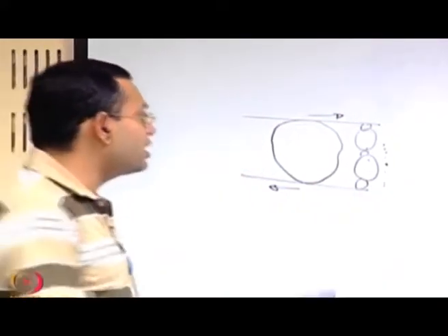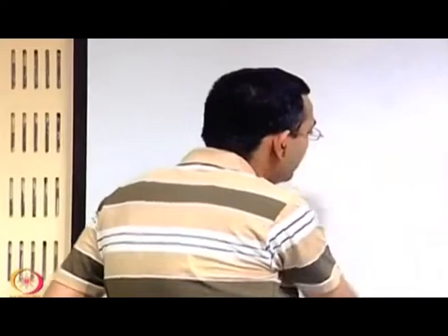One important understanding from this cascading mechanism is that in a turbulent flow the interaction between eddies is very important, and this interaction makes possible the exchange of momentum fluctuation, energy fluctuation, and so on. Therefore we must have at least an overall idea of how the exchange of momentum takes place because of fluctuating components between several eddies, or maybe two eddies at a time.